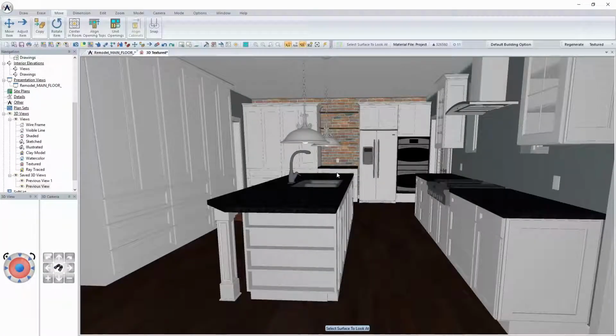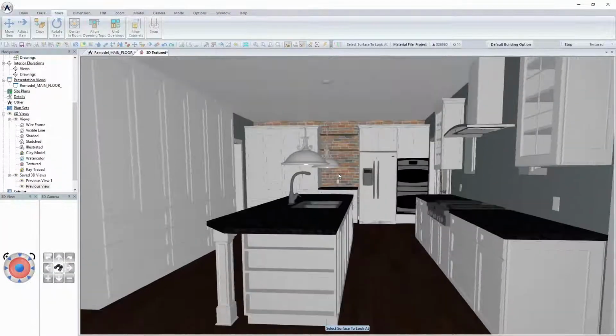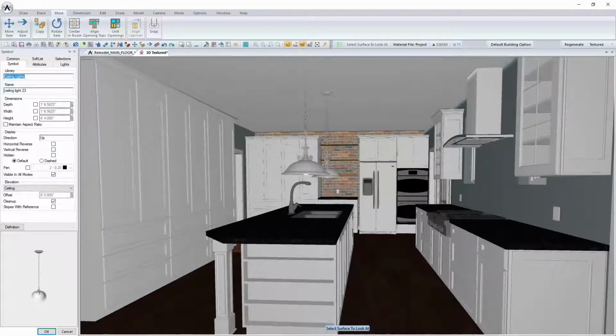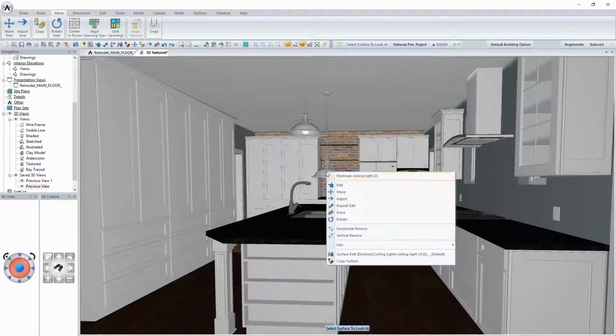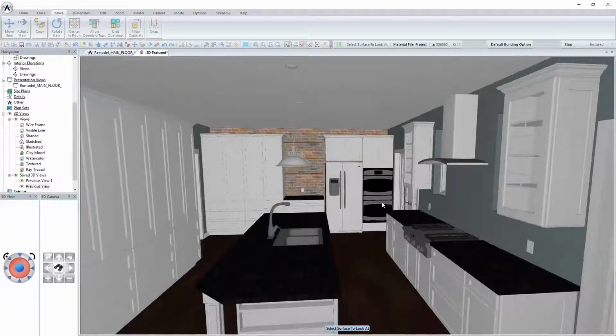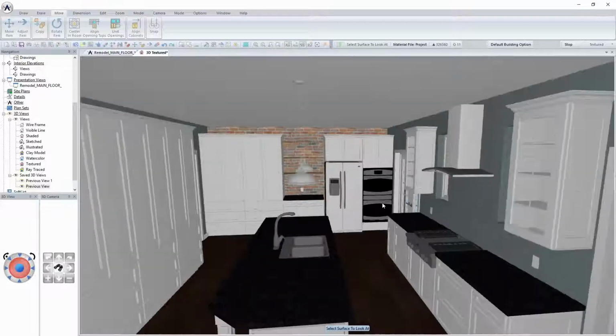As you can see, we've got these light fixtures now, and these can be modified because they're obviously a little bit too much as far as the height is concerned. So I'm going to change this height to 3 foot 4 inches, or even 3 feet. I'm changing what the dimension looks like, and then I'll just repeat edit this on that light fixture there. And that's our pendant lights that we're going to have there.